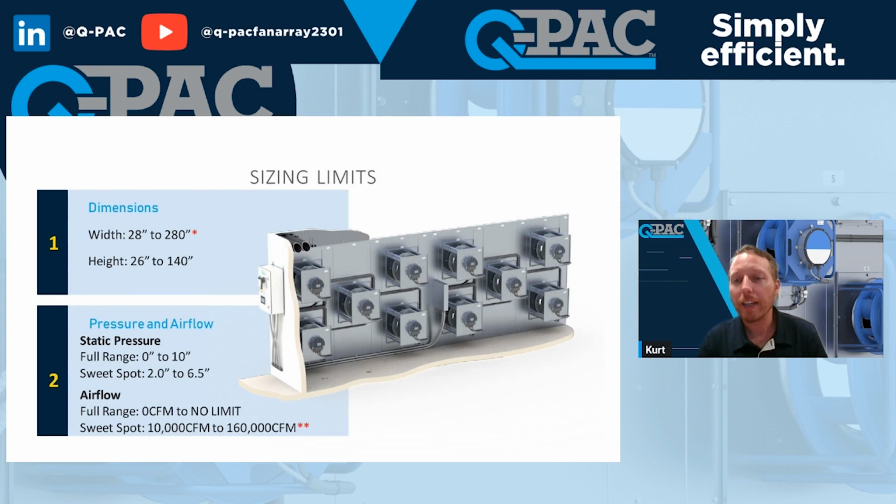But 280 is the limit in Quips. So if you need to go beyond that, or you need more than 2 fan arrays like you see in this picture, then just add a note in the specials column. Height-wise, 26 inches is as small as we'll go, and 140 inches is our limit. That's the limit of the sheet metal that we buy.